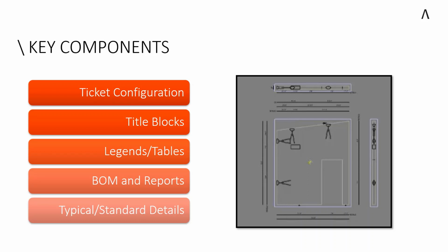What we are talking about is a ticketing engine that derives its information directly from the model. So that when the model is correct, the tickets are correct, they are consistent. The tickets of identical mark numbers can be assured to be consistent with one another. The software checks these things.